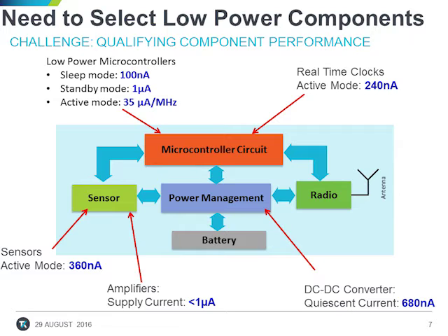The muscle spec for a microprocessor has always been higher operating speed, gigahertz clock rates. Now for low power, the suppliers are offering a power versus speed trade-off with ultra-low sleep mode currents. Note that many of these components have ultra-low currents in the hundreds of nanoamps range.